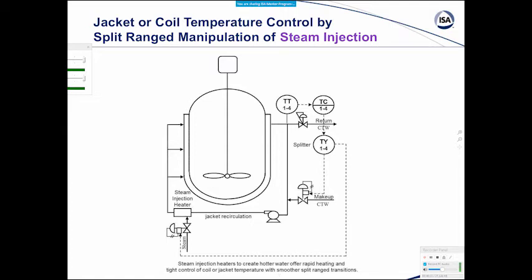Of course, you still have to be concerned about the control valves, and when they go closed and then they go open, you want to make sure that they do not have much stiction at the closed position. So again, you can make a very smooth transition and not get any stick slip going on, particularly since the stiction tends to be highest near the closed position.